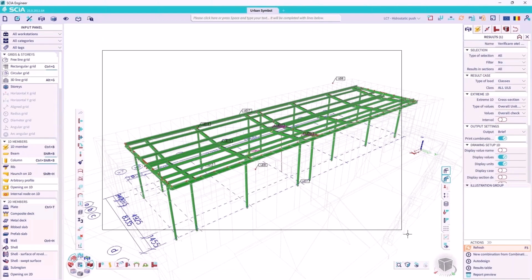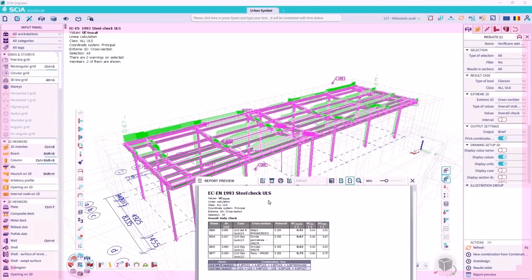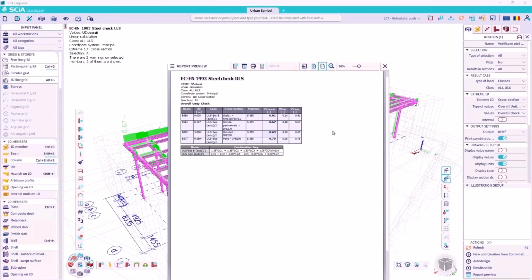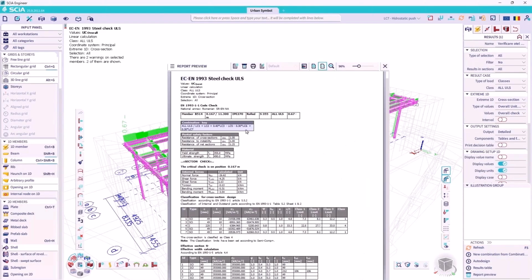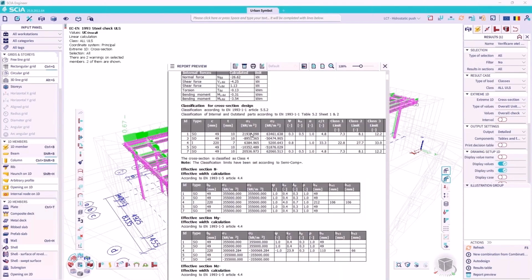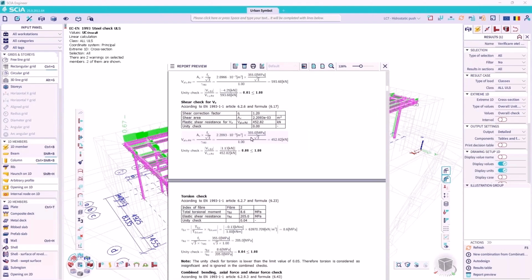Now going onward, we'll focus on the steel structure. As I said, it's a hidden steel structure, and it's hidden within some walls which are placed non-symmetrically. So each frame is unique here. So we can instantly make a structural check of steel. So we see the unity check, which is the worst combination or worst checks between section check and stability check.